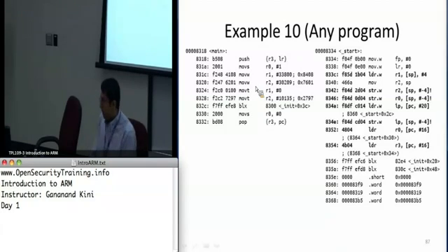Any question here? Should be pretty straightforward. So it's just showing you the different addressing modes. So here you have pre-indexing with write-back. It's going to take the stack pointer here, subtract 4, and then write that back into the stack pointer after storing the value of R2 at that address location. Okay.